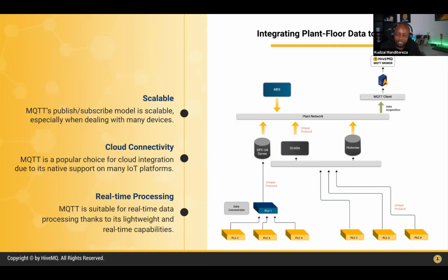This really allows you to scale your system, because as you add more components, it doesn't affect how that data is being consumed. If you scale to 10,000 devices or 10,000 data points, it doesn't really matter, because everything is being published to that central hub, which is an MQTT broker. All you need to do is make sure that your broker is able to handle whatever amount of connections or traffic is being directed to it. So you're able to scale your data that way.